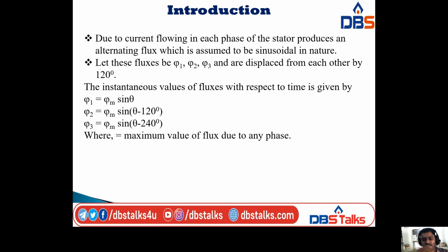So here we are applying the three-phase supply to the stator winding. After that we have current in each phase of the stator windings, and this produces an alternating flux, which we assume to be sinusoidal in nature.